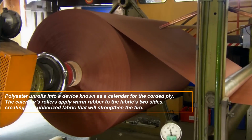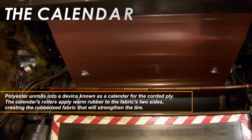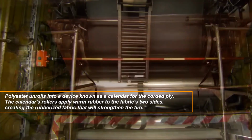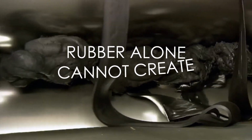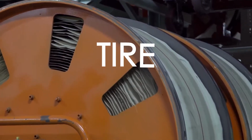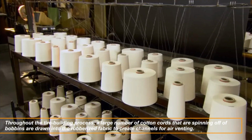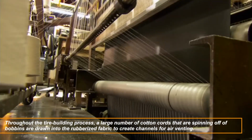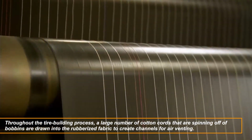Polyester unrolls into a device known as a calender for the corded ply. The calender's rollers apply warm rubber to the fabric's two sides, creating the rubberized fabric that will strengthen the tire. Rubber alone cannot create a tire that is robust enough. Hence, this fabric ply is required. Throughout the tire building process, a large number of cotton cords that are spinning off of bobbins are drawn into the rubberized fabric to create channels for air venting.